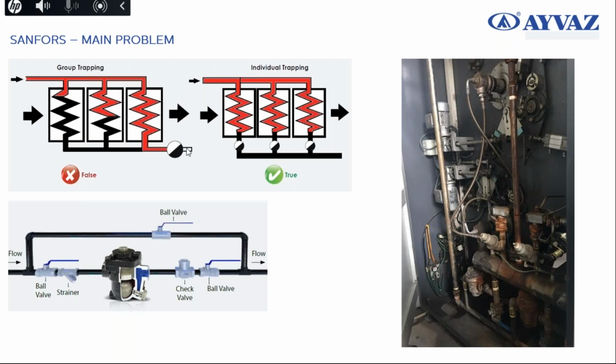When the steam reaches the steam trap, it will prevent the steam leakage to the side of it. But when it's locked, if there is any condensation, it will not pass through the steam trap. Why? Because there will be steam. And it will make heat loss, and it will reduce the capacity of the heat exchanger or the cylinder.